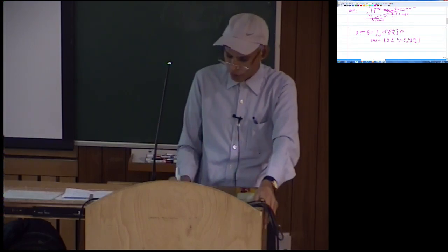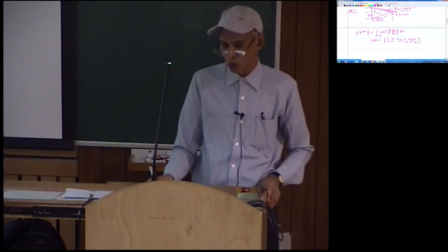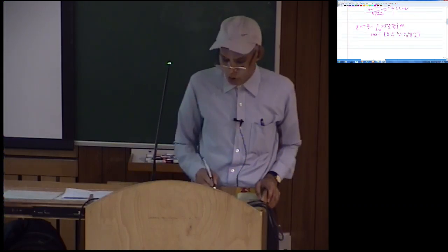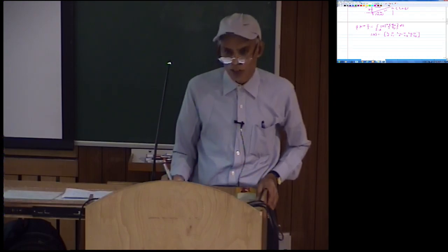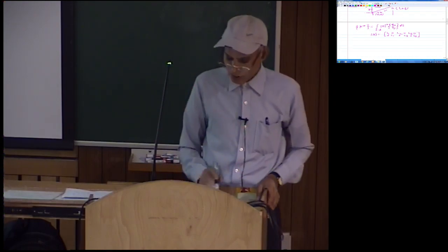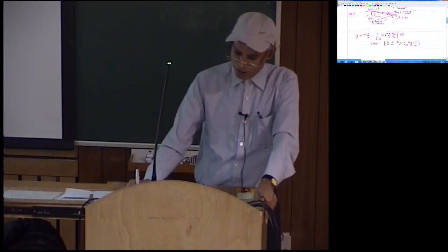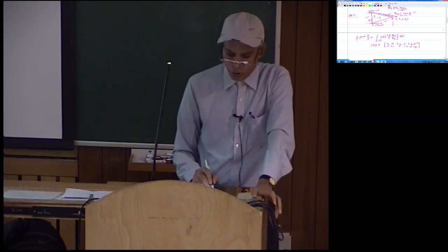The first row into the vector of elemental degrees of freedom U1, V1, U2, V2, U3, V3 gives you U, and the second one gives you V. So this is your H, and Qx is given as 100x, Qy is given as 0. So you multiply this and then do the rest of the calculations. You can write L1, L2, L3 as the ratios of areas as we have discussed in the class, and then you do the integration.